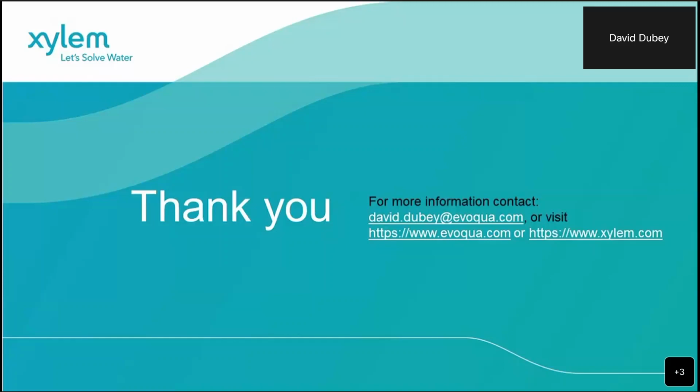Are systems designed to add lime for alkalinity, or how is insufficient alkalinity addressed? Just as you said, adding lime or another carbon source is the typical method to correct for low alkalinity so that nitrification can occur.